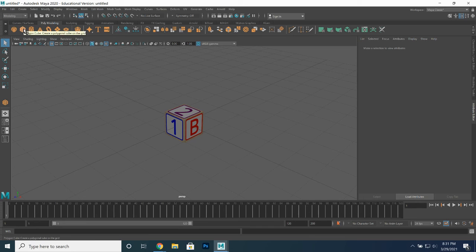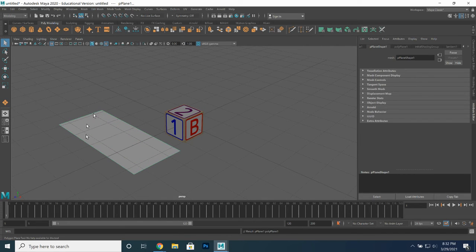And I'm going to do a kind of flat area light. If you've ever worked with a camera or a lighting set, you may notice those big black boxes with the white front faces on them. They're called soft boxes. Basically, they're just a flat surface with a light behind it, and this is white. We're not going to build the whole box. We're just going to turn this into the flat front surface of a light. And the way we do that is by drawing out that plane. So I used this tool right here, dragged myself out a plane on the bottom, and then I'm going to switch from modeling to rendering.